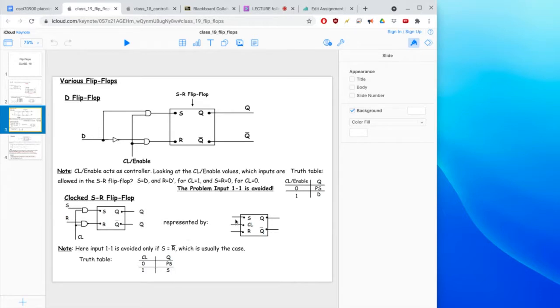I said there are really two inputs. However, with the function Q in this truth table, we don't care whether it's 1 or 0. We only care whether it's a previous state or a new state coming from S. Because the value of S is a valid outcome for Q, really there is only one input, and the input is clock. For that reason, we only have 2 rows in this truth table. How about that? Are there questions about that statement?